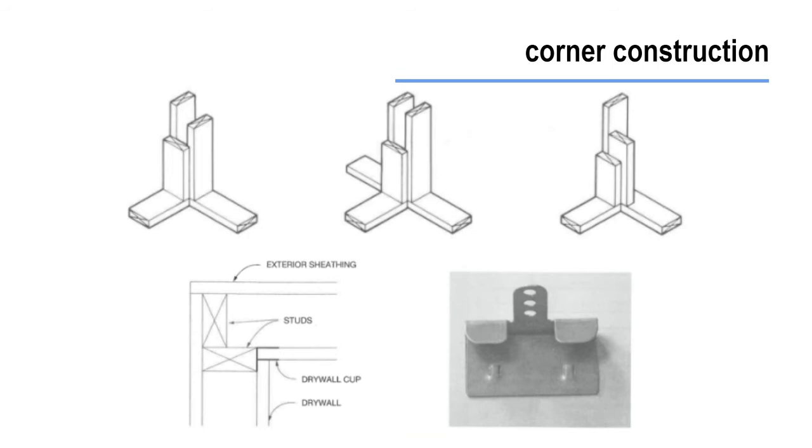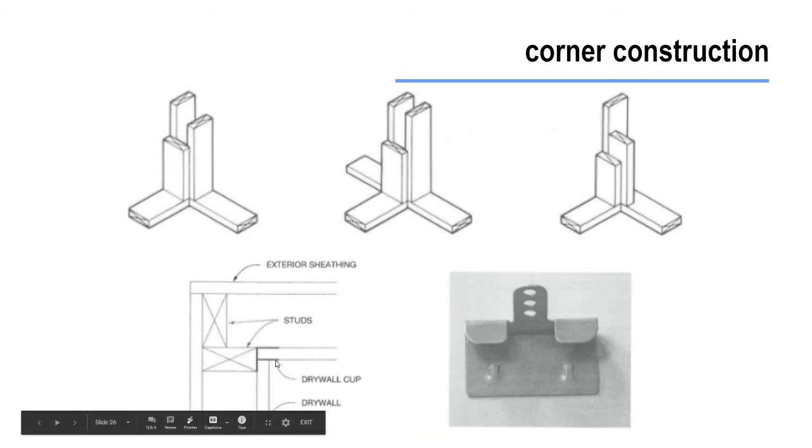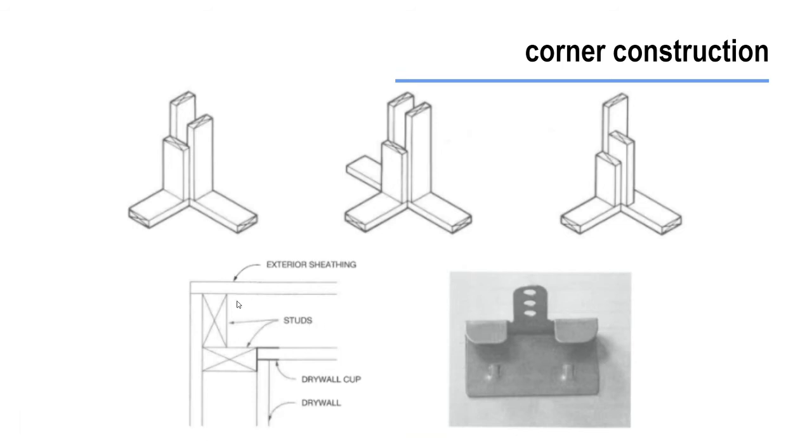To reduce that heat loss for advanced framing, only 2 pieces are used, and a metal clip is used to connect the pieces of drywall together to reduce the need for wood, and now I can fit insulation all the way into every little nook and cranny in here.